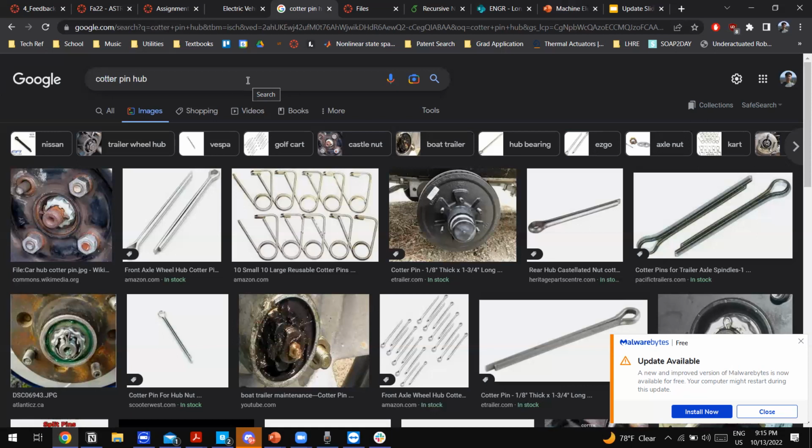I guess I'll just tell you, center locks still scare me, and I have no clue, to be honest. You've got one huge thread that you machine yourself and treat yourself, and if it fails, your driver dies. Well, maybe not that, but yeah. Whereas 4 bolts you know the strength of relatively well. Yeah, Kieran was saying the same thing, but because of those rims, it's kind of worth it to switch. At least that's the decision he came to. The other option is flat out worse. The only benefit then is that you have preload. The question I would ask is if you're confident enough to machine it, because I don't think I am.